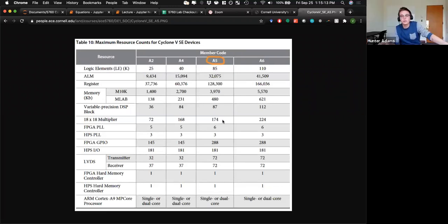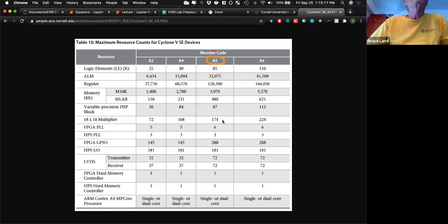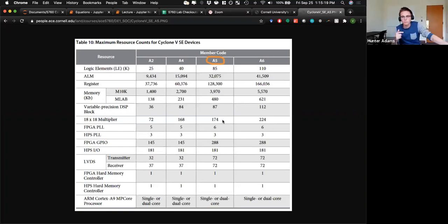And the next thing I'm going to show you is in Quartus how to open up the compilation reports for when you're compiling your project that will tell you how much of all of these resources your design is using. Because what the exercise is going to be is to compile this. You can figure this out on pencil and paper. It's a good exercise to figure out on pencil and paper, for example, how many multipliers do I think I'm using in this project?